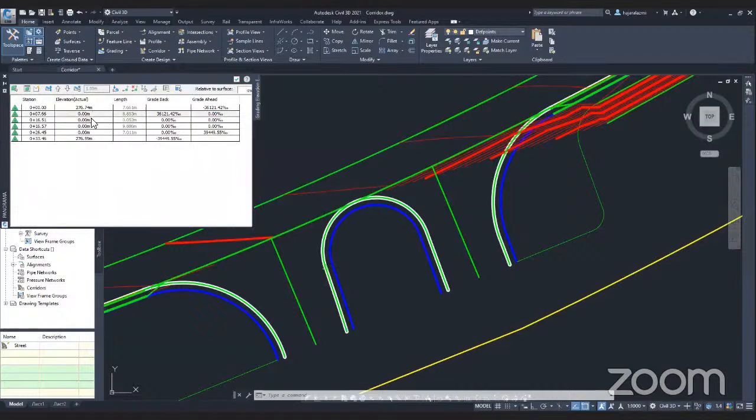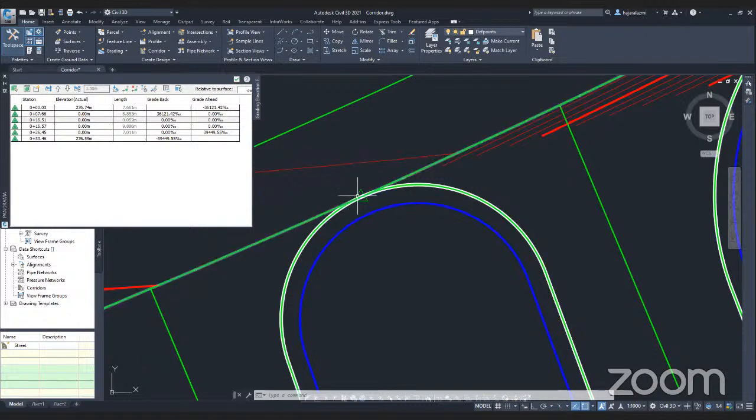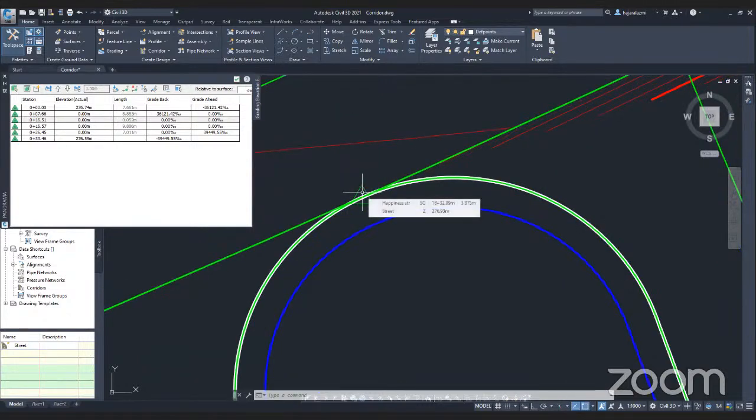So I'm just going to use the constant grid. But before that, we need to put in this elevation. So we go again on here and zoom in slightly big, and then hover to this side. And then we can see the elevation being put under the street there, 276.93. So I'm just going to copy that, 276.93, and I click on enter.